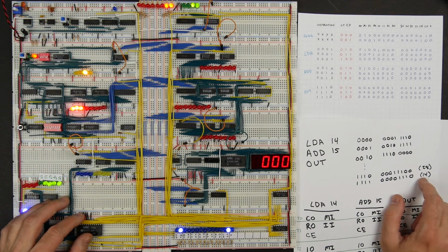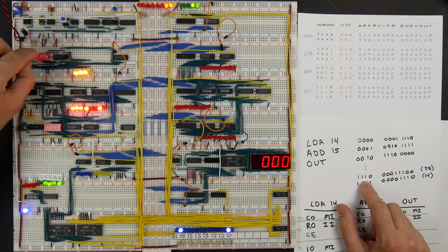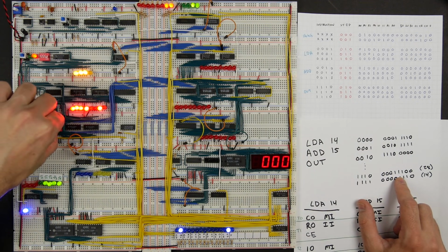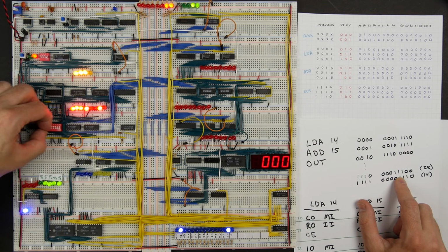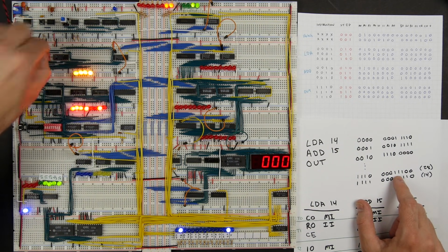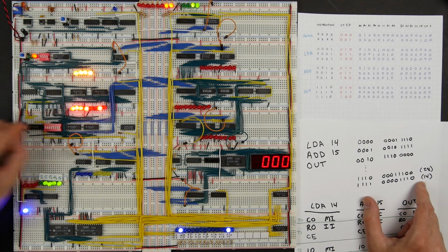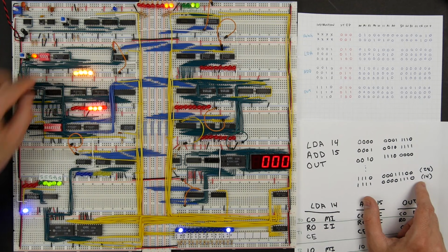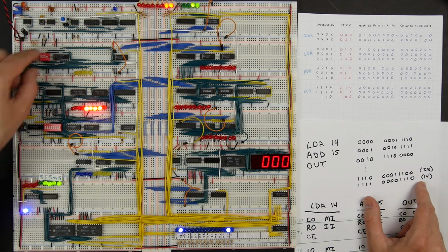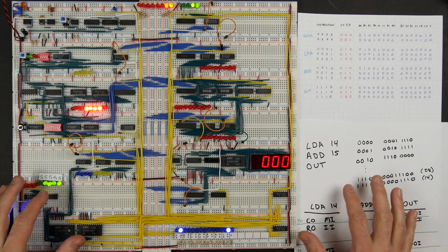That's a 28 and a 14. So in address 14, we want to put that 28, so that's 000, 111, 00. There's our 28. And then we'll go to address 15, and we want to put in a 14 there, so 1110. So there we go. And if we go back into program mode, we can start to try to step through our program.